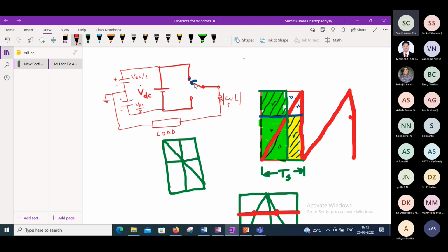and that too at high frequency. So it induces a high amount of switching losses, and a significant size of filter is needed. Also, having a two-level converter for high power applications, like high power drives, invites many other limitations, like